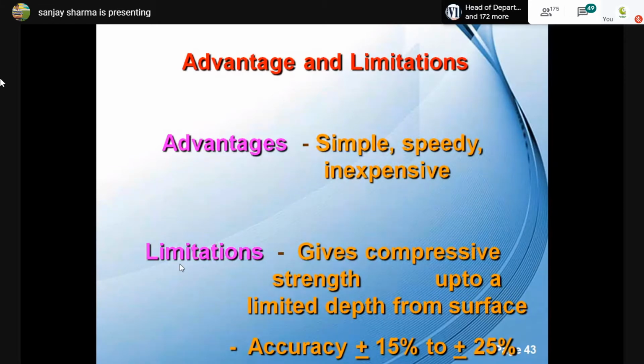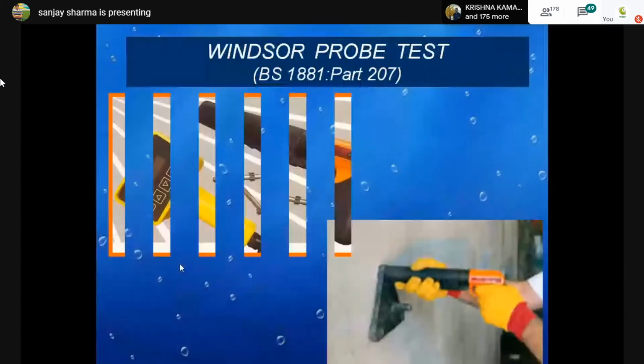Recently, we were doing one test on concrete, and one of the third-party auditors came and said, "Okay, let us see what is the accuracy of your hammer." So he brought a cube, the impact was given, and according to our correlation graph, we said the strength would be in the range of plus minus 2. We said it was 42 plus minus 2. So he said, okay, let us test it. He tested the cube, and we got exactly the same value. So if your equipment is well calibrated and checked, you may get very good results on site.